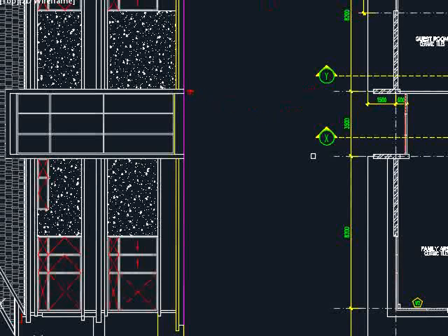which if you compare side by side, you know that this is a continuous wall as a part of the architecture. You will need to consider this. Now it is up to you to decide whether you want it to be a reinforced element or just a stack of brick, which you need to ensure the stability of this part.